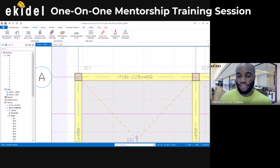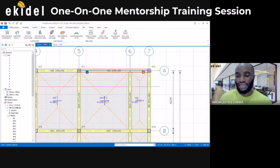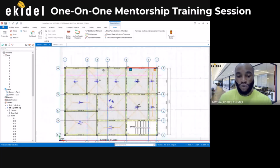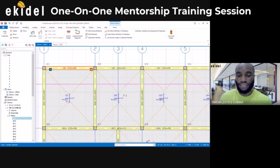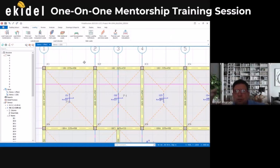For example, this beam now has an end on this place. And also this other beam here has an end at this place. So at this end now, I will assign a hinge end. And also at this end will be a hinge end. While the other places here that have a continuous end, they'll be fixed. Understand? So you can have moment redistribution, no?